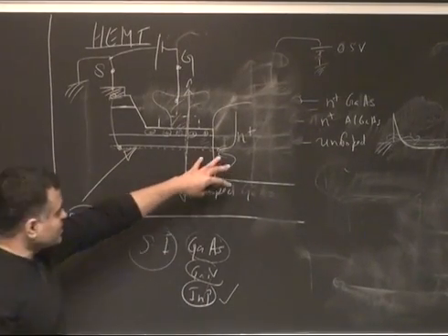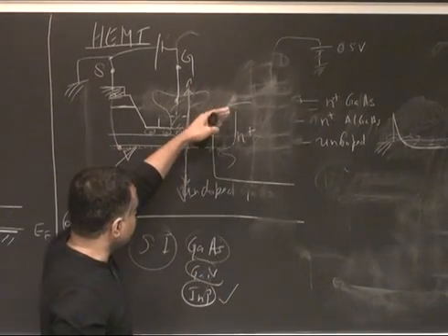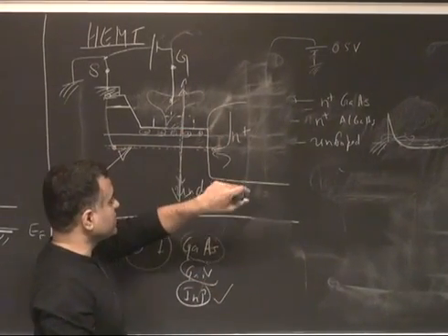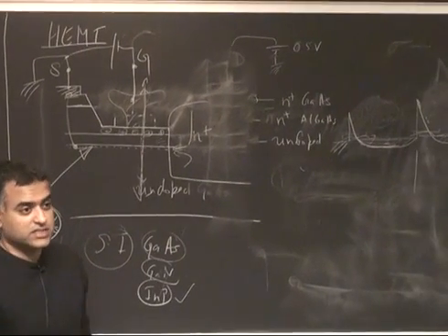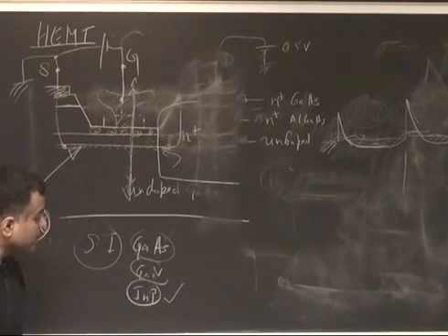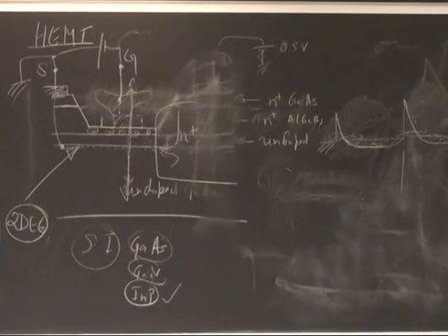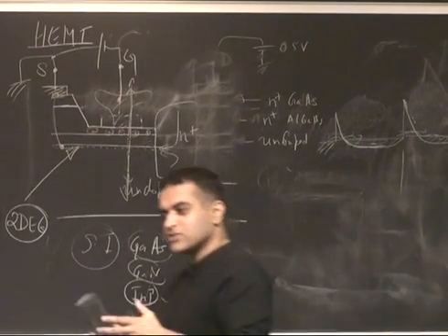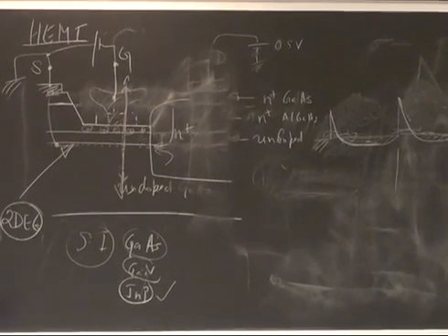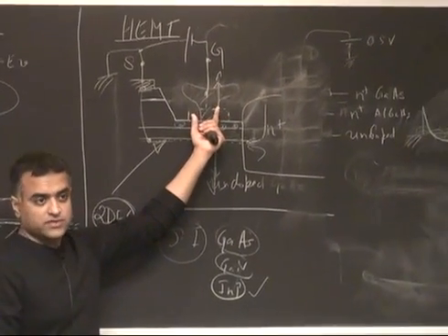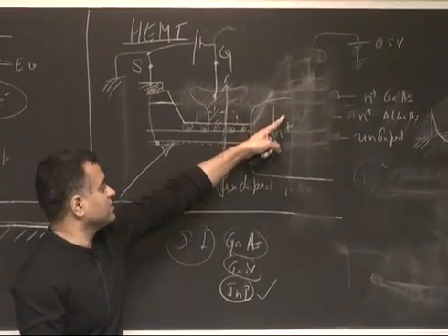This technique is actually used in silicon too. They create the MOSFET and then etch down, put it in a UHV CVD system, and regrow a silicon germanium region for the contacts in a silicon transistor process today. So the contacts are all regrown. One of the reasons the contacts have become so important, and why it's important to lower the resistance, is because the devices have gotten so small. The resistance is now completely determined by the outside. The channel is very small now, at 100 nanometer, 50, 12 nanometer, 15 in silicon MOSFETs. So all the losses and resistances are there.